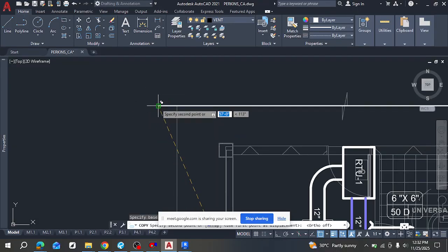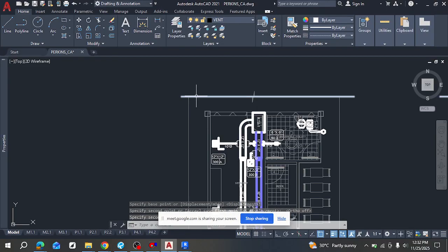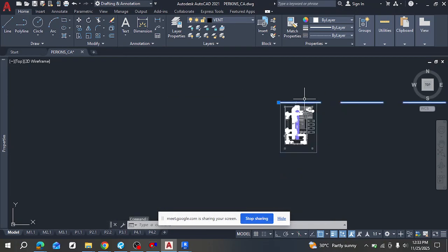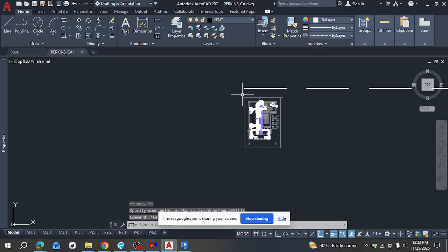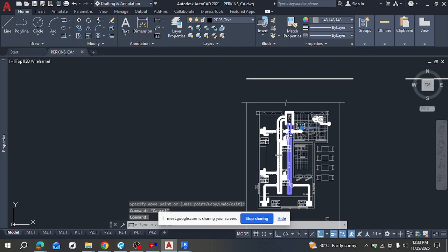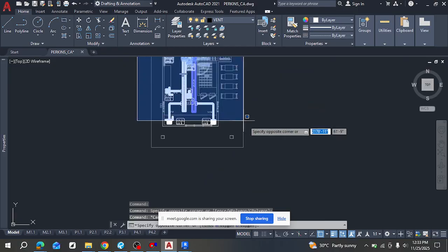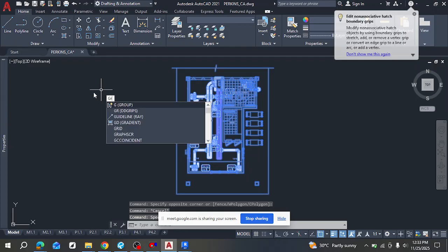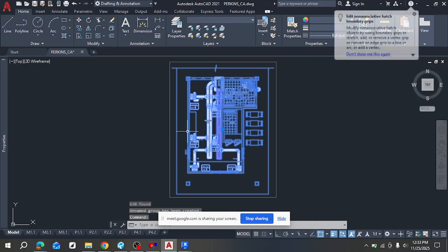Now I want this line to be, remember that this line I took out was the length of this place, right? Before I do that, let me move it up. I want to group these projects so that it does not scatter. Grouping, if you notice, if you select one, is different. There are different things. See? So now if I group it, I'll select everything as one. Then later, if I want to, I can ungroup it. To group, you type in group, see it here, GR, and then group comes up. So now this whole system is selected as well.